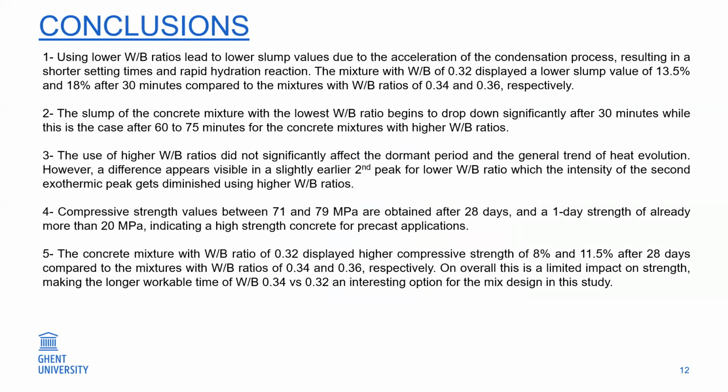In this slide, which is the conclusion and is representative of the most important findings of this research study, the most important findings can be listed as below. Using lower water to binder ratios leads to lower slump values due to the acceleration of the condensation process, resulting in a shorter setting time and rapid hydration reaction.